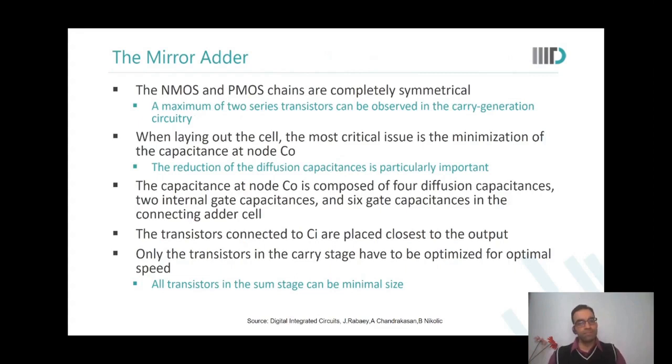Because the carry has to propagate through the stages of the adder. Yes, because the carry out of your stage will go to the next stage, then a new carry out will be generated for the next stage, and so on, at least if the propagation is going to happen. So that is what we are looking at, that we have to reduce the capacitances, we have to reduce the delays. As you reduce the capacitances, power and delay will automatically reduce.